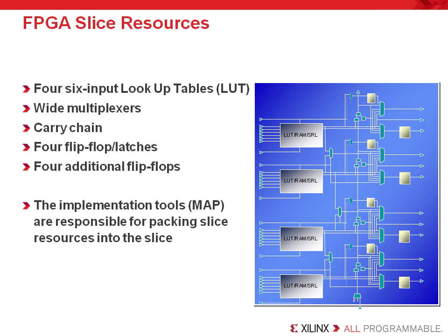This is because ASICs are faster than FPGAs, and it's much easier to get good speed from an ASIC with suboptimal HDL coding styles used. Now, this is highlighted when you consider what you would get if your combinatorial logic had 7 inputs. Because the LUT has 6 inputs, your synthesis tool will be required to add a second LUT in series with the first. This would then dramatically increase the delay associated with this path and cut the maximum frequency possible for your design.